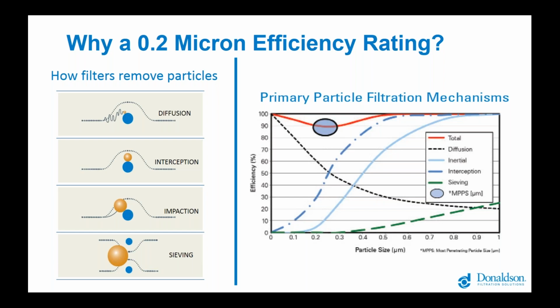And at the other end is diffusion, or random movements of very small particles that are imparted by other molecules in the fluid stream and the energy of the system. And that random or Brownian motion will increase the likelihood that the particle will contact the filter media. And that's really where the magic happens. Once that contact has been made, things like electrostatic forces will cause that particle to remain adhered indefinitely.